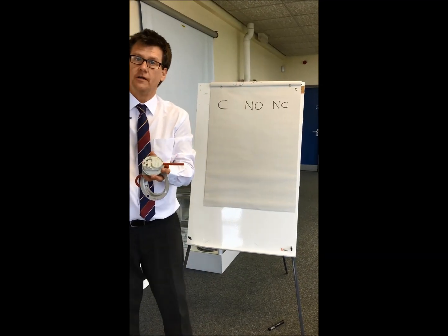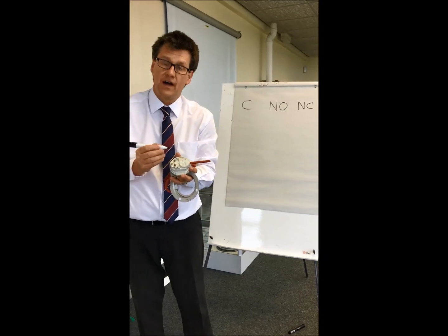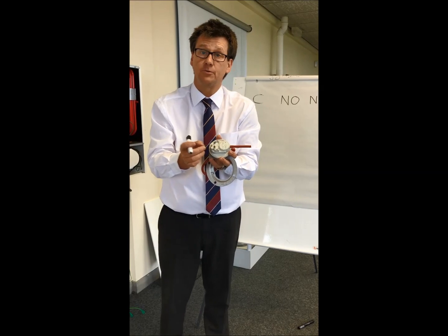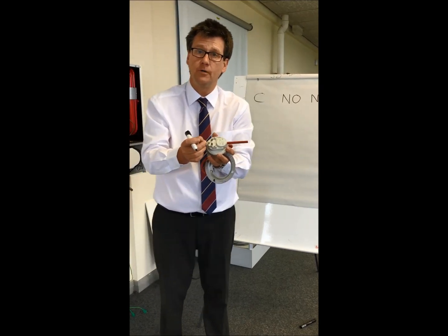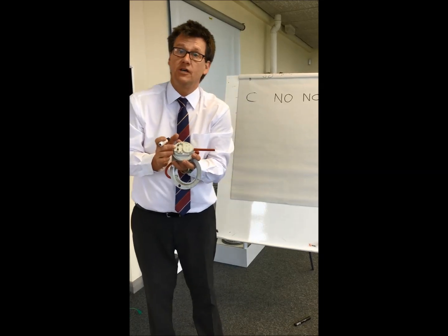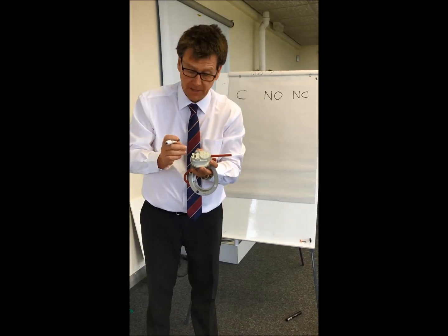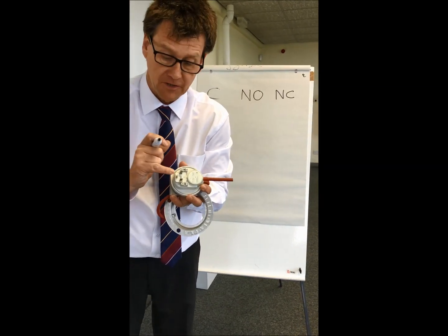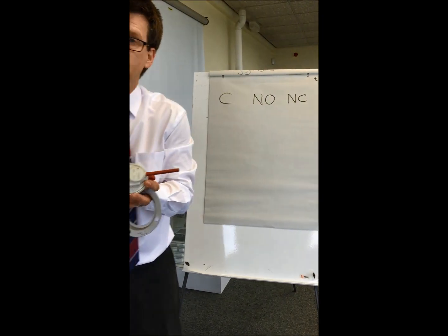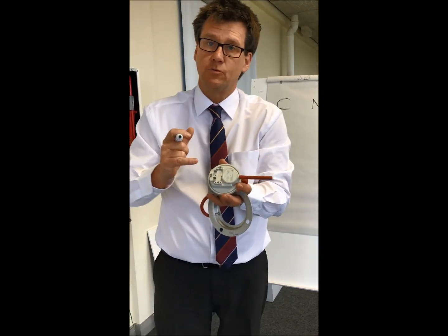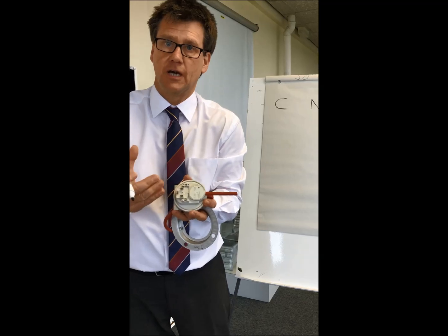As time went on, we found that we had 2 wires, but 3 tabs, and one of the tabs was covered with a red or an orange rubber boot. Then as time went on, we found 2 tabs, and the 3rd tab had disappeared. Well, it hadn't disappeared, it became a flat piece of metal on the air pressure switch, because that flat piece of metal was still a usable part of the air pressure switch. And that usable part was the normally closed position, guys.